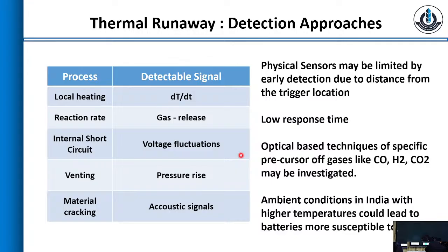But those are external temperatures. Internally, there might be some reactions still taking place. Once you stop putting water and remove the blanket because the fire has extinguished, there could be internal reactions taking place over hours. That can again lead to reignition, because internally there are oxygen molecules and hydrocarbons available.